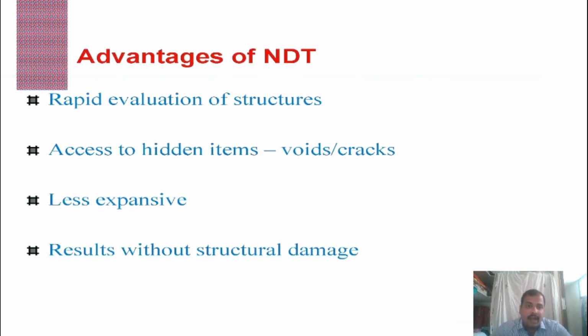Now, what are the advantages of NDT? By using these NDT techniques, we can rapidly evaluate our structure. We can access hidden items such as voids, cracks, honeycombing and so on, and it is much less expensive as compared to the destructive techniques, and we can achieve the results without any structural damage to our structure.